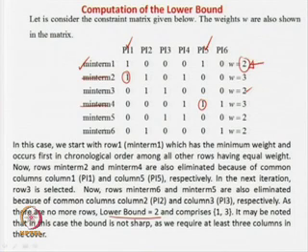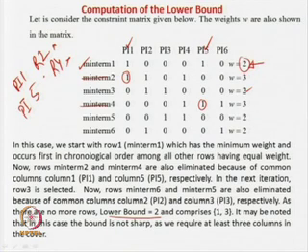Now, here is a problem. You are quickly reducing the matrix, but in essence what will happen? You will cover minterm 1 either by Pi 1 or by Pi 5, but not both. So, there is a choice: if you cover it by Pi 1, then you can eliminate row 2, and if you use Pi 5, then you can eliminate row number 4, but not both.